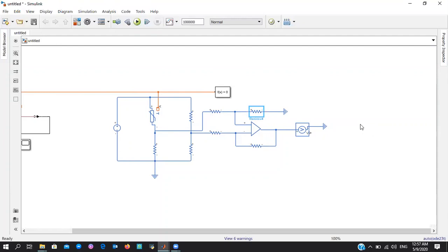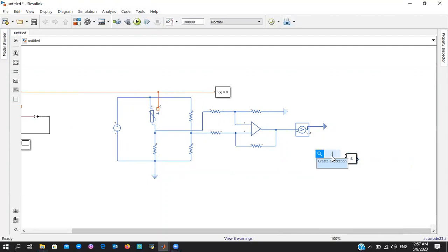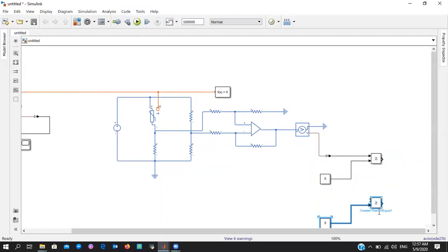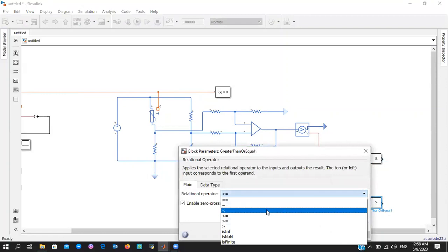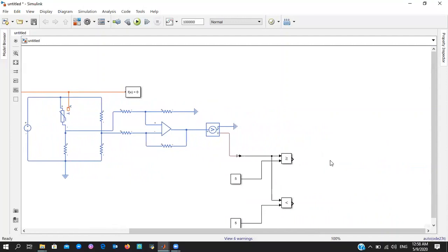These are 100. Now we will need to build a comparison system. So it gets greater than, and we need a physical to simulink converter. One over here like this. Here a constant value 5 representing 5 volts. Go ahead and copy these. This one is here. This one is going to be less than K.